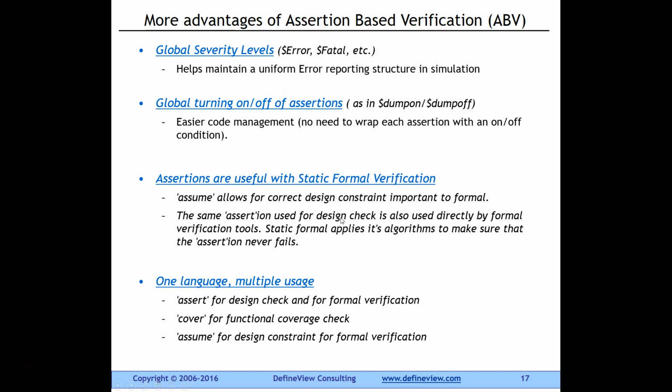And the next advantage is obviously, like I just said, in this one language you can assert, you can cover for functional coverage, and you can assume for either constrained random verification or for static formal verification.